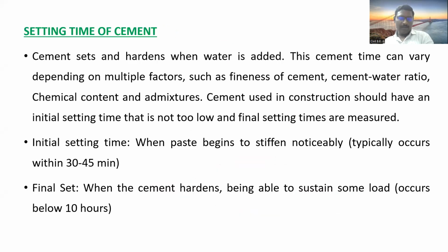So the next physical property of cement is the setting time of the cement. So what is setting time? This is a very important physical property. Cement sets and hardens when water is added. If we add water into the cement, it will set and it will harden.